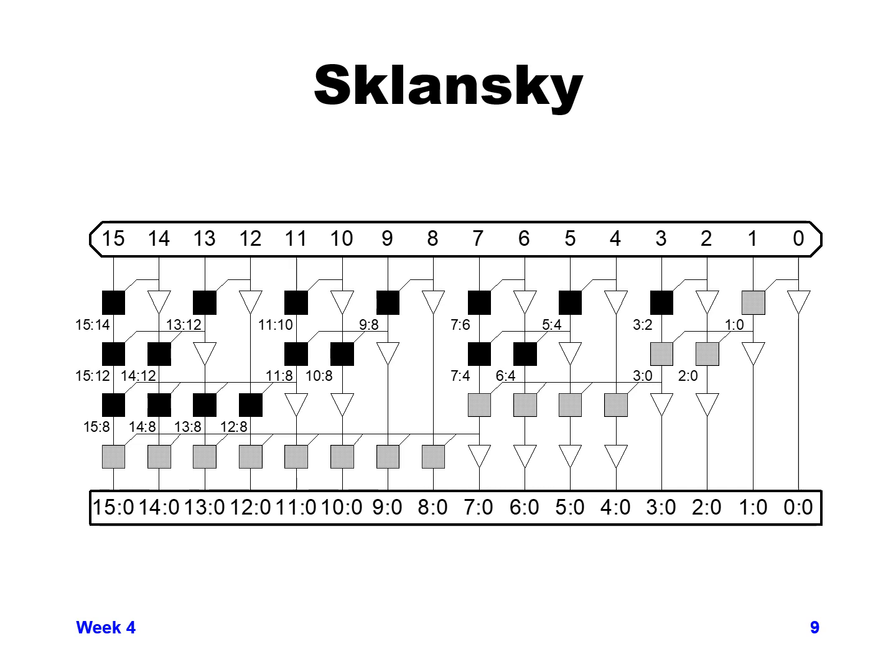And then if you go down to the third stage, looking from bit 7, starting at the top of bit 7, you have a black square and a second black square, and then the gray square. That gray square is now driving basically 8 bits plus the buffer. So it's basically driving 9 bits worth of data. So you can see it's pretty heavily loaded the way this design is.